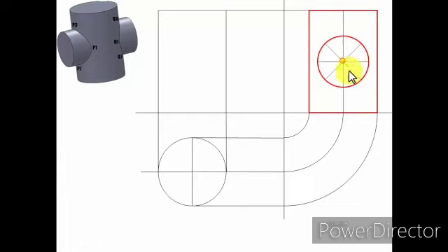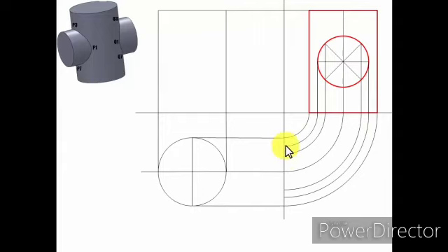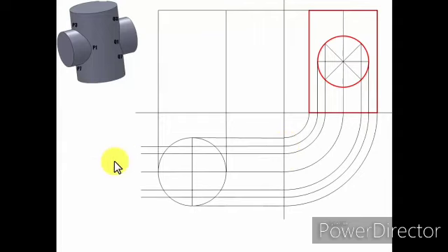I've divided this circle into 8 equal parts, and now with the help of this side view, I'm going to create the top view of this horizontal cylinder, and it's going to look something like this. Project all these points with the help of these lines in the vertical downward direction, and then rotate them about this point in the clockwise sense, and then bring all the points towards the left hand side of this top view. From here to here, the length I've assumed to be equal to 120 millimeters.